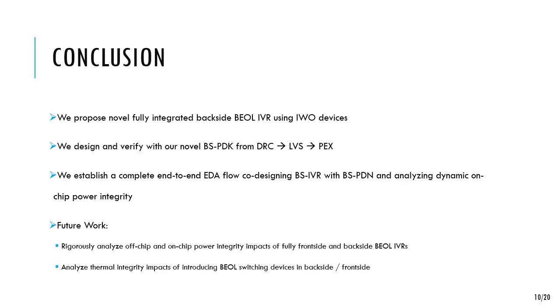Additionally, we also establish a complete end-to-end EDA flow to analyze the on-chip power integrity impacts when we introduce back-end-of-line voltage regulators, especially in the backside, and we have to co-design the power delivery network to work around the voltage regulator as well. However, there are some shortcomings of this work, and as for future work, we want to